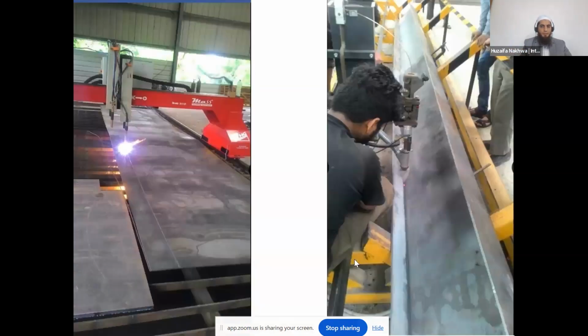Okay, so the upper panel, which is flanges and web, are both cut with a plasma cutting machine or shear machine, and then placed on a rack. Okay, where we can weld it with a SAW machine, or different types of welding systems. Okay, so alternate weldings are there.